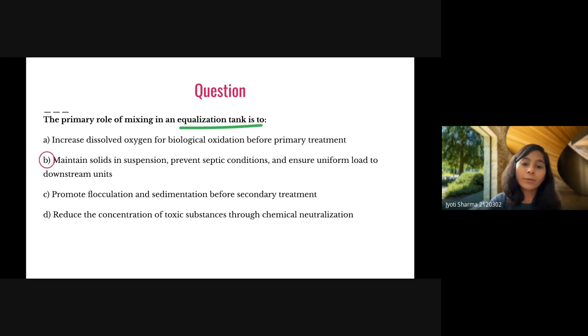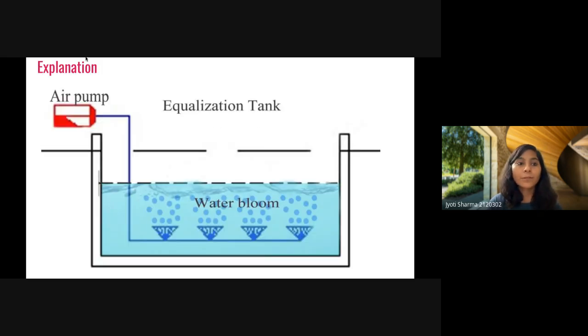That's how an equalization tank is used. To make the wastewater uniform, we have to pump some air, and that's how it will mix everything in a uniform way. So this is the equalization tank.